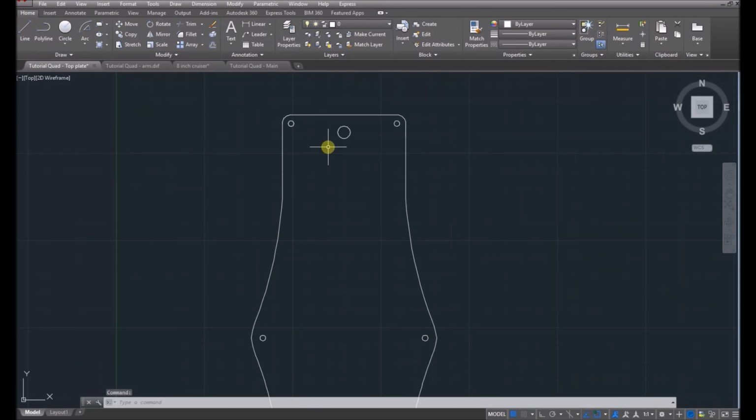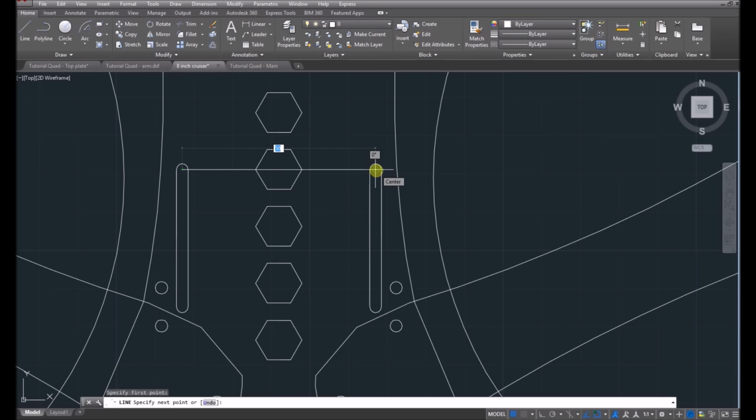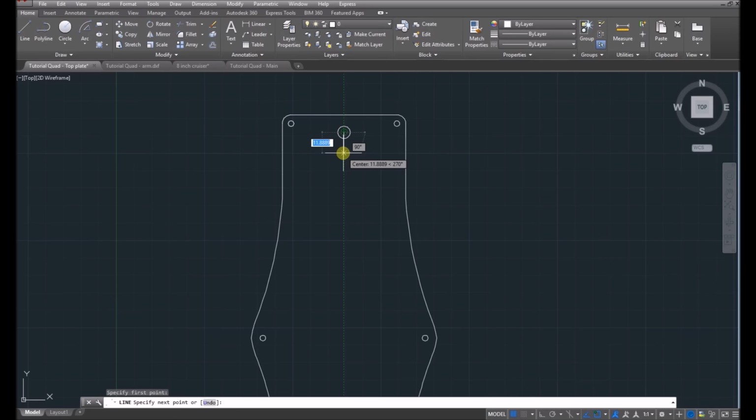Okay. So now you need to think about what battery you're going to use, and probably measure it. Like for this frame, I accounted for the fact that I'm probably going to use a really big battery. So I went a 50 mil distance for the straps. So that's a fair bit. Now I'm going to come down from the SMA a little bit before I do the strap holes. Realistically, you'd probably want the straps in the middle of the battery. Let's just say we're going to go one strap in the middle of the battery.